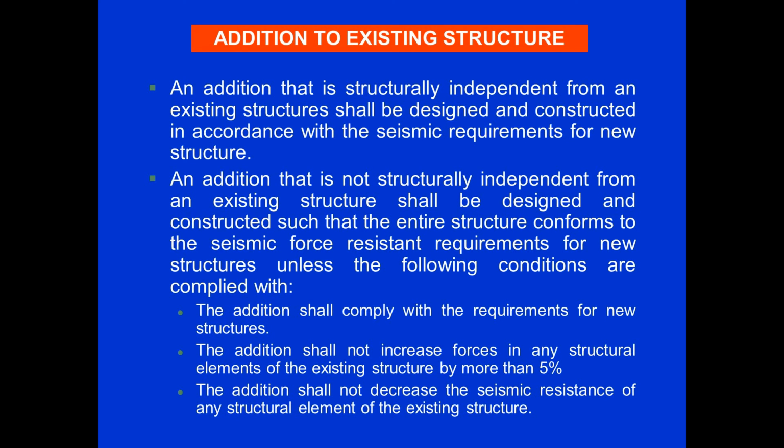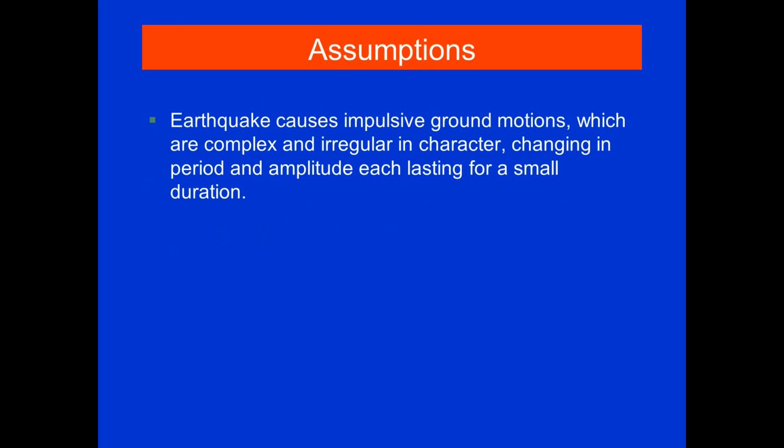The addition shall comply with the requirement of a new structure. The addition shall not increase force in any structural element. The addition shall not decrease the seismic resistance of any structural element of the existing structure. So these are the assumptions on which the earthquake design is based.